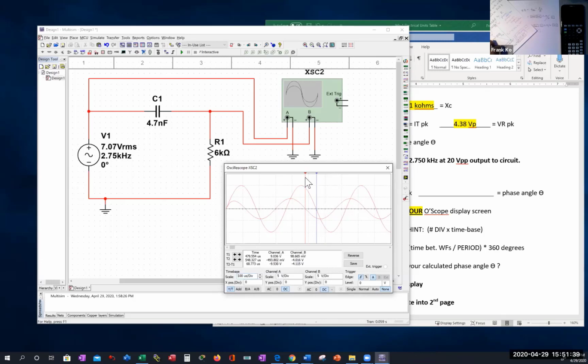And we discovered that the voltage on the resistor was on channel B. Channel B shows a positive lead over here, coming up to the top of the resistor. And that showed on the lower waveform as something less than 5 volts. It may be a little hard to read here. I'm going to change the scale of channel B so that I can magnify this. It's a little taller. I'm going to change the scale on this guy so it's out of the way for channel A. So channel B at 2 volts per division is now more clear.